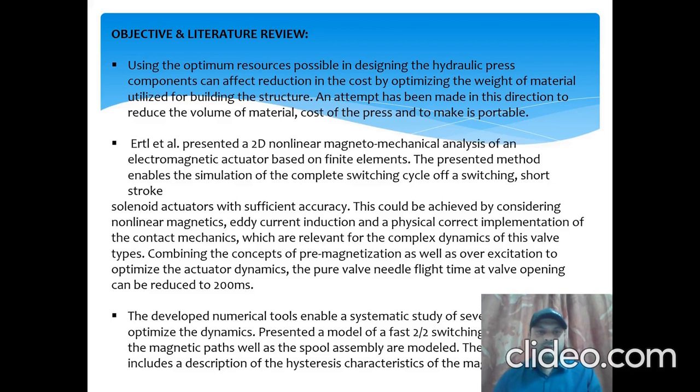Ertl et al. presented a 2D nonlinear magneto-mechanical analysis of an electromagnetic actuator based on finite elements. The presented method enables the simulation of the complete switching cycle of a switching short stroke solenoid actuator with sufficient accuracy. This could be achieved by considering nonlinear magnetics, eddy current induction, and a physically correct implementation of the contact mechanics, which are relevant for the complex dynamics of these valve types, combining the concept of pre-magnetization as well as over-excitation to optimize the actuator dynamics.